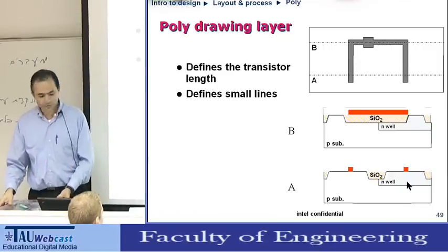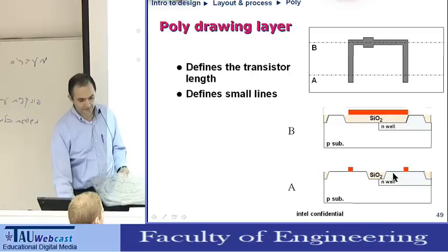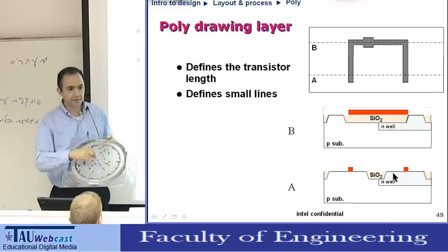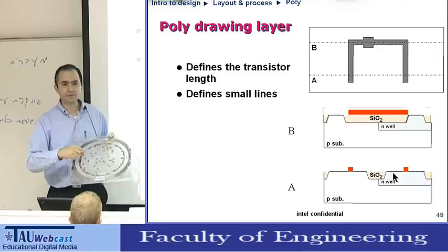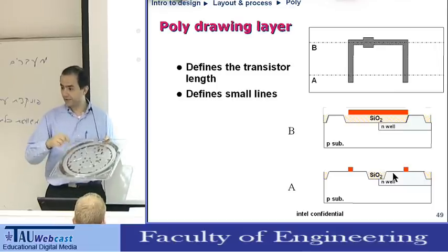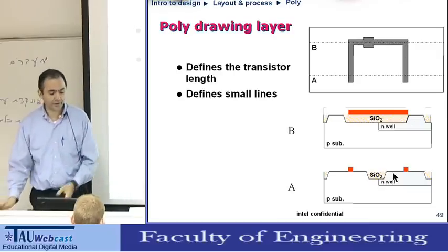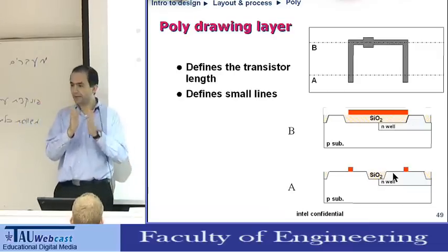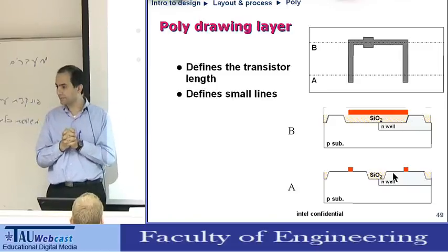We need the over etch to make sure that the oxide is not removed only from this area here on this specific die on the center of the wafer, but also in the edge dies where the etch rate is different, so we might have etched less, and also in areas in the wafer where the structures or maybe the polylines are more dense and the etch rate between them is lower. Okay.